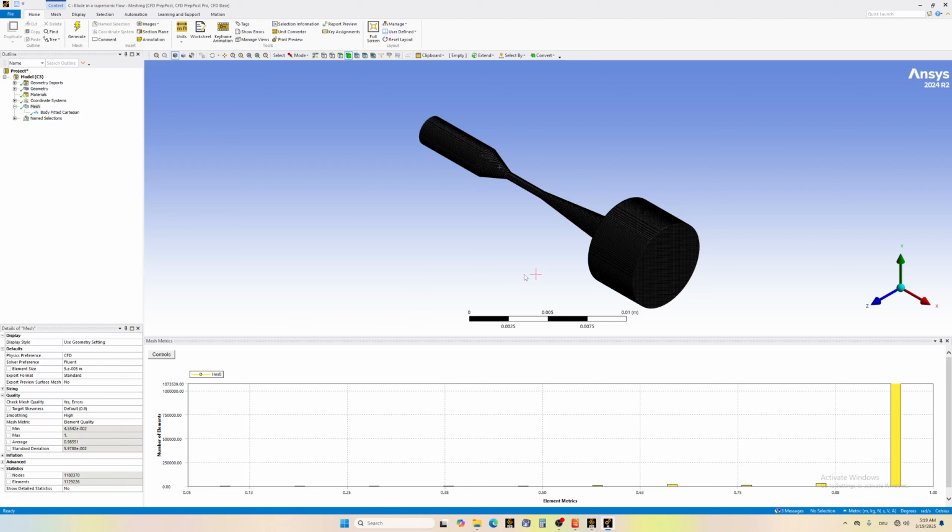Always run what are called mesh independence studies. So you increase the number of cells in the mesh until the solution doesn't change anymore. You have to be careful about this one. So you monitor the shocks, you monitor whatever is required, and make sure that it doesn't depend on the mesh size. All right.